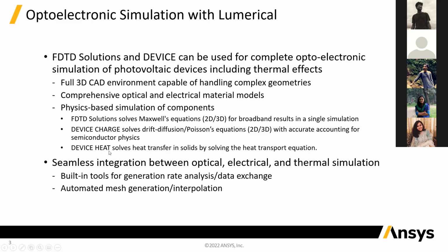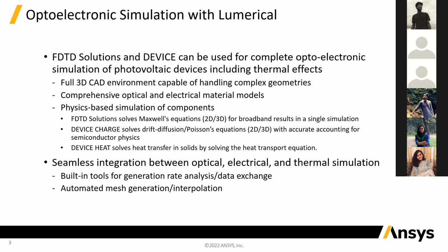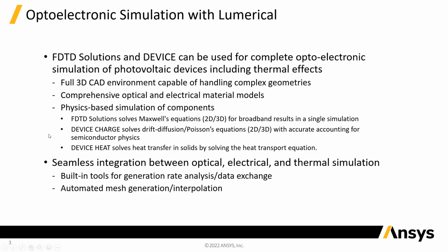And then finally, the heat solver allows you to model the heat transfer. And so in a solar cell, when it's sitting on your roof, for example, like a simple solar panel, it can get pretty heated up as it absorbs the sunlight, and that higher temperature can affect the performance of your device. So sometimes you need to do thermal simulations as well and capture the heating effects in your simulation. So it can be not only optical and electrical, but also thermal simulations could be needed.